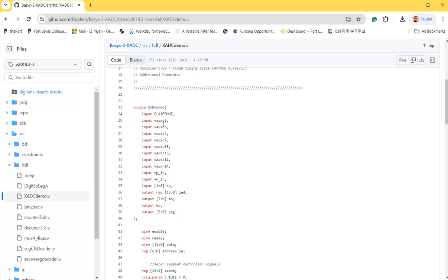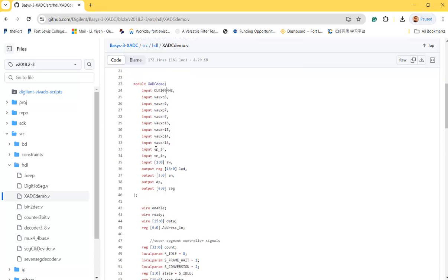And you can see these are the keywords, right? These are the pins from the constraint file, so you don't want to change them. And clocks have a different name. If you are using this name, you have to change it accordingly in the constraint file. As you know, we are using just clock, simply CLK, right? Anyway, these are the pins, and these are also instantiated but not being used. I don't know why they still have to do it.